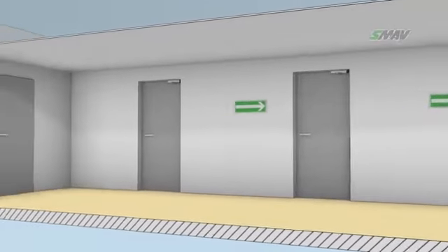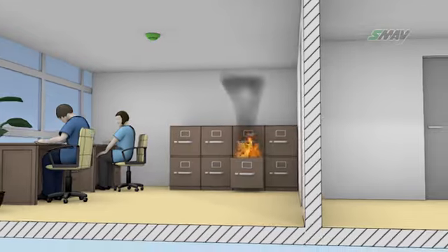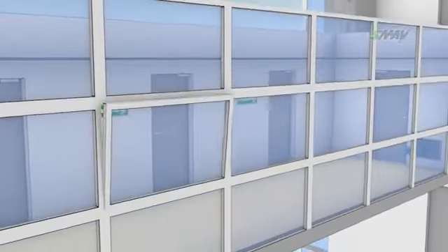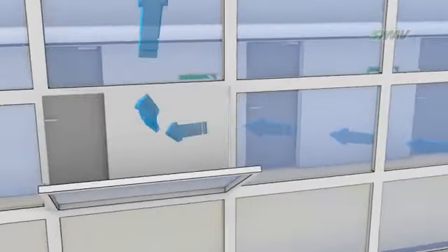Designing appropriate air release in the corridor will ensure that the smoke will be extracted from the corridor. Air may be extracted by a mechanical smoke extraction installation or naturally; for example, window ventilation may be used.